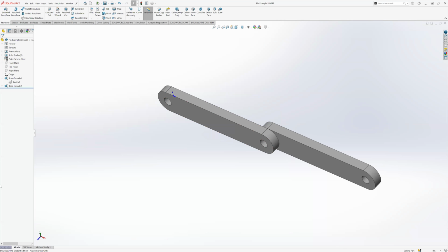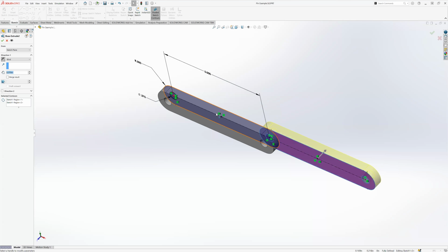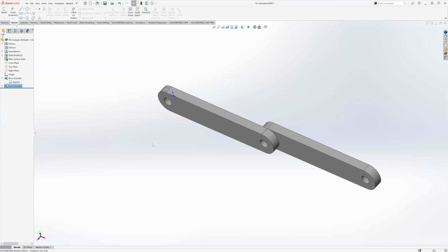Two solid bodies. Yeah, two solid bodies. Kind of how I did that is, first, I did one sketch. I extruded this sketch this way. I extruded the same sketch in a separate feature going this way. And I unchecked this merge result, which means even though the bodies are technically touching, they're still going to be separate, because obviously I don't just want to have one big block of material. That's how I did that. Okay, so we have this now. Let's go and save here.